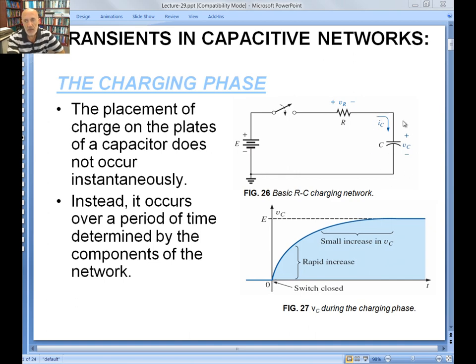As far as capacitors, it is a first order system. By that I mean if you have one storage element in a system, the system becomes first order, which means the differential equation describing the dynamics of that system would be a first order differential equation. We're going to see later in this chapter that the capacitor actually does differentiate the voltage waveform. So the current I sub C will be some function of the rate of change of the voltage with respect to time across the capacitance. If the capacitor voltage does not change, it stays constant, there will be no current flowing.